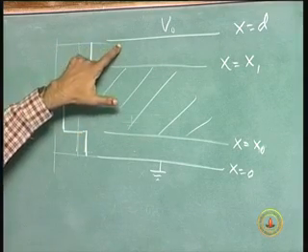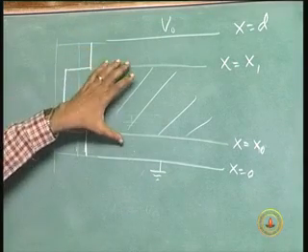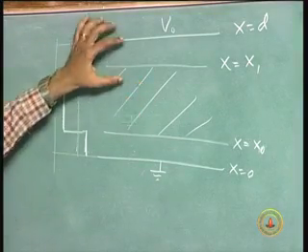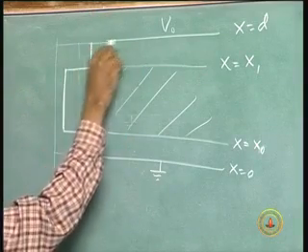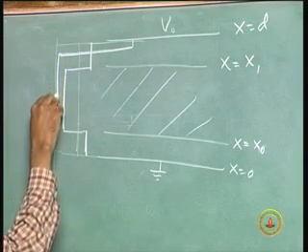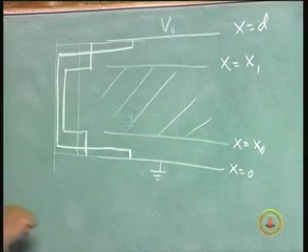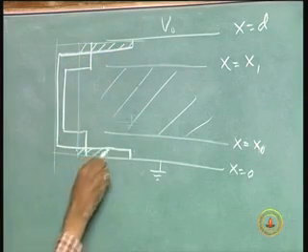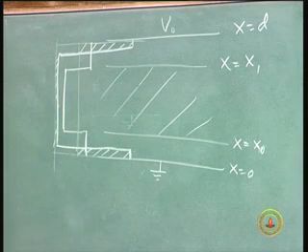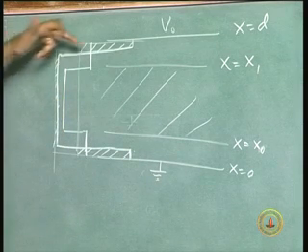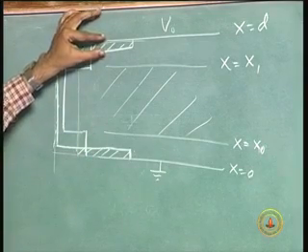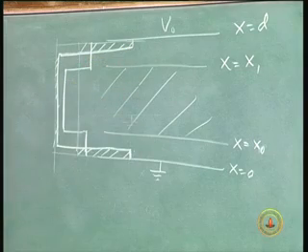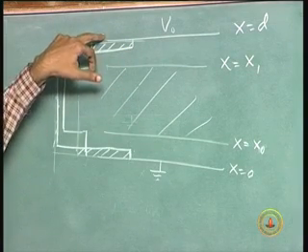But having a high electric field means having a lot of induced charge. So, by putting a large dielectric constant material inside this capacitor and making it fill most of the gap corresponds to something like this. That is, I have got an average that is this much, but that average is made up of very large electric field here and very small electric field in the rest of the region. And by putting this gap as a very small quantity, I am actually creating a very large electric field here, and that is what is giving me a large amount of induced charge and that is what is giving me a large capacitance.